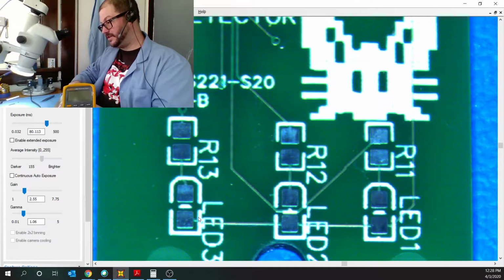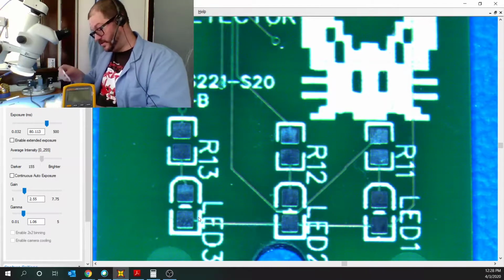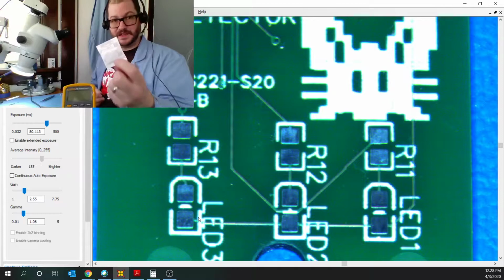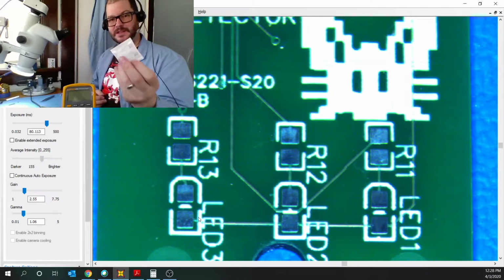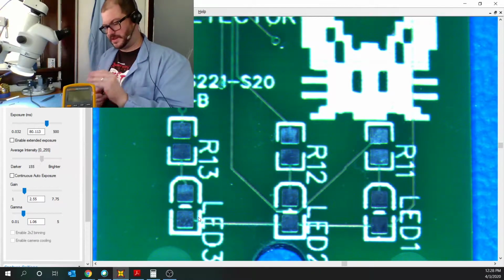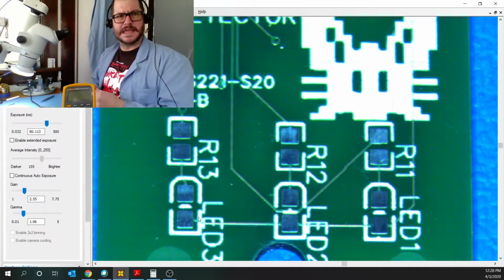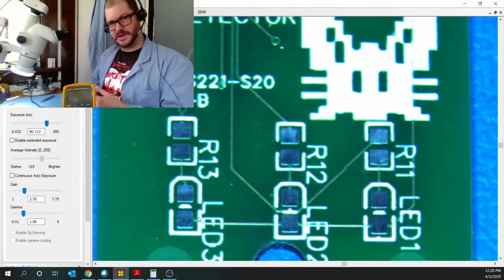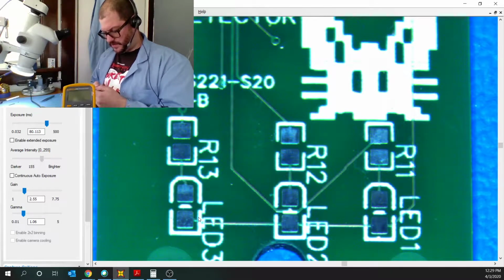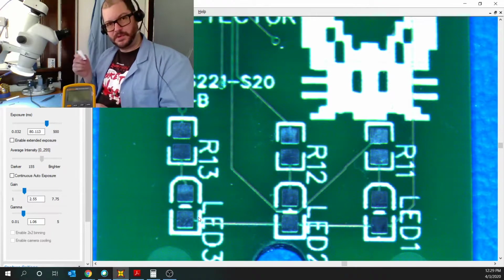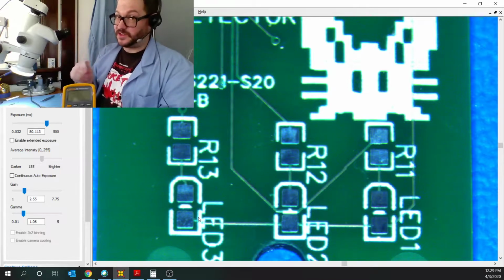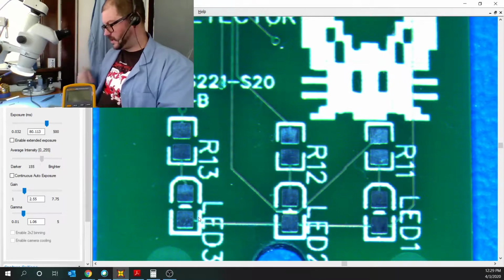The other thing that comes on the inside of this bag, in addition to hopefully the parts, I don't see where they are just yet, is a desiccant bag. This is a silica bag that contains silica powders that help get the moisture out of the air and trap it on the inside of this bag. Specification MIL-D-3464 type 1 and type 2. What you're supposed to do is put this on the inside of the bag, and if any moisture does get in, this will get to it first.